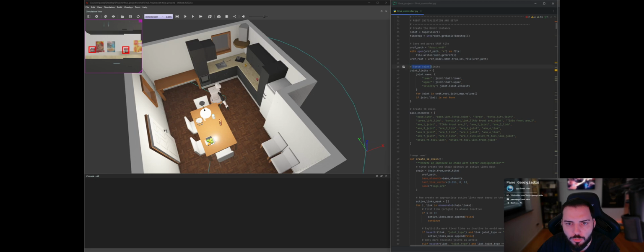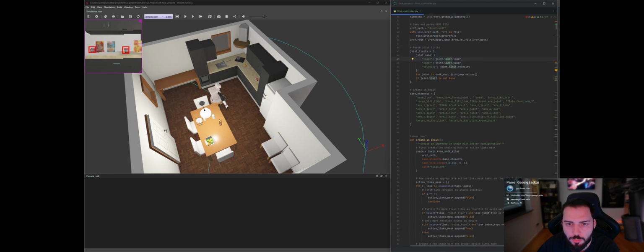Here you're initiating the joint limits, and then this is creating the inverse kinematics chain. You're starting with the base link, even though you're not controlling the base link. Well, for this purpose, we're not controlling really the base link. We're controlling the torso for some things, but not necessarily for arm grasping. But what you need to do when working with the ikpy library is you need to list the joints in succession, from the beginning all the way to the end.